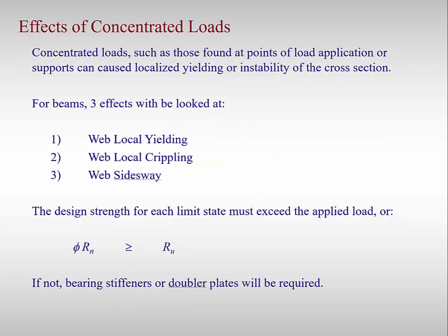Now we want to look at the effects of concentrated loads on beams. We will look at 3 effects: web local yielding, web local crippling, and web side sway. Note that the issue is with the web. These provisions are given in Chapter J of the specifications.